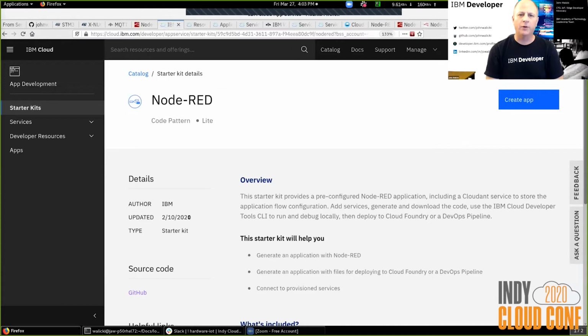OpenSTLinux, which is a variant. Oh, I didn't talk about that. Let me go back. The board, I said running Linux, so it doesn't run Raspbian. It runs an Open Embedded Linux derivative, all totally open source, called OpenSTLinux. And so I compiled it and I installed Open Embedded here, a Yocto-based distro. So those of you familiar with Linux distributions, I'm a Linux expert, so that was relatively straightforward. I've been compiling kernels for 21 years or something silly.